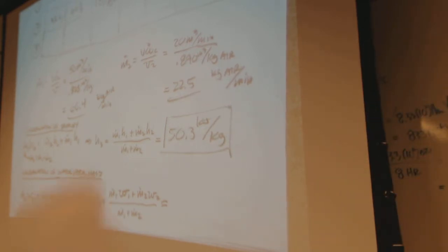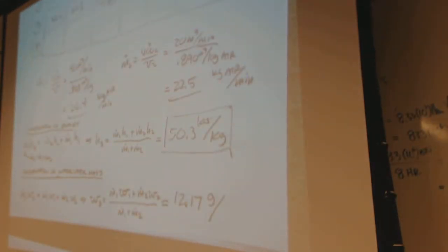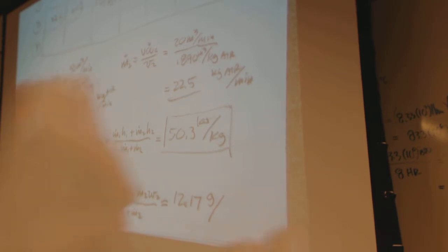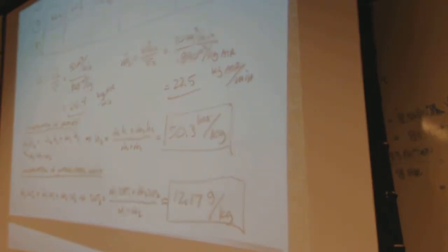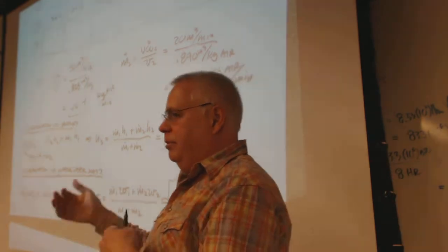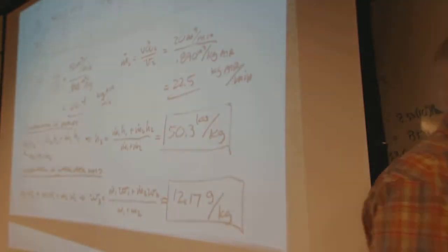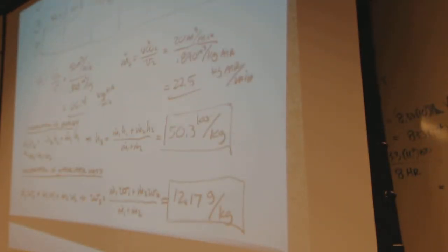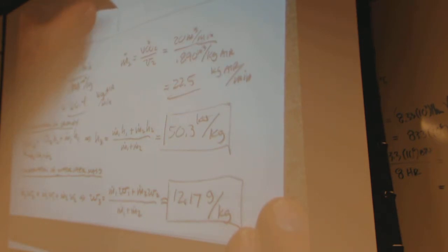12.17. And that's the grains of water, right? This one isn't grains. This is metric, and it's grams of moisture per kilogram of air, of dry air, meaning air without moisture in it. Grams per kilogram. There are some of those scales that are in grains. Some of them are in kilograms per kilogram. Some are in pounds per pound. So now, based on that,